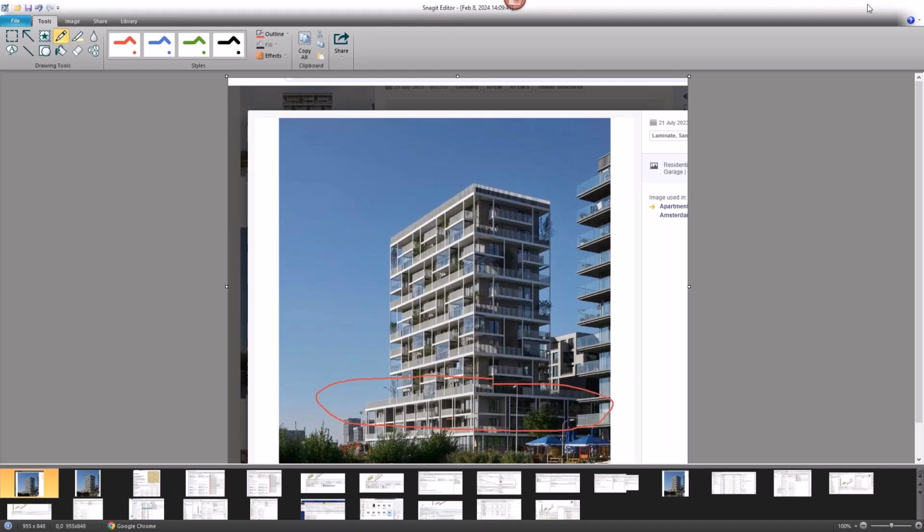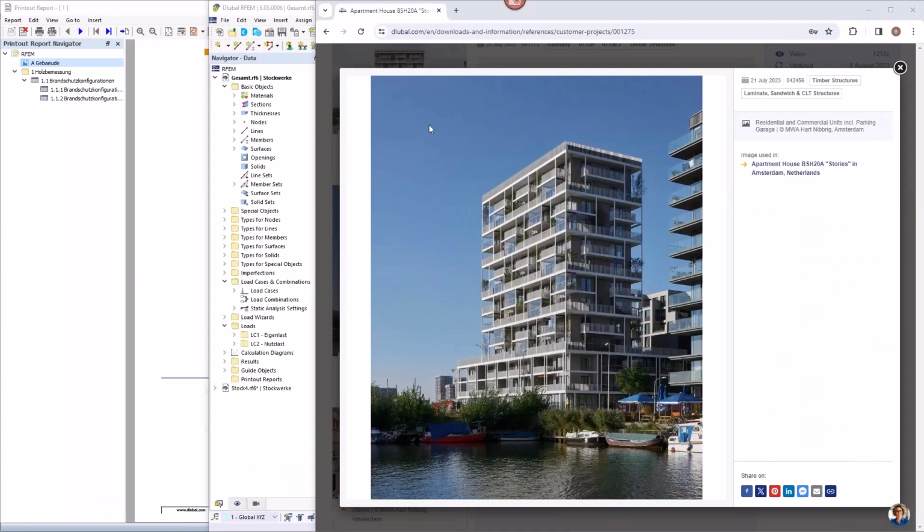So how can you do this? You can first of all model it in 3D and regard all construction stages analysis, all this stuff in the 3D model, or you can model it in 2D, and then you have to connect each story via the option load transfer. And this is the option that I'm choosing here today.